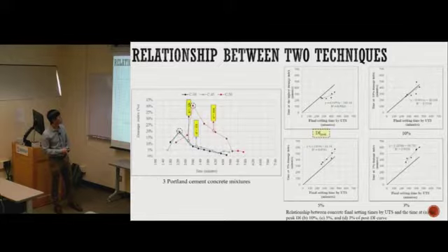The minutes of setting that you're proposing, 240. It's just the set time from when they place the concrete, right? Yeah, after they place the concrete. They usually don't wait that long, and they still get good results. Maybe they use the accelerator. That's the only case they don't.